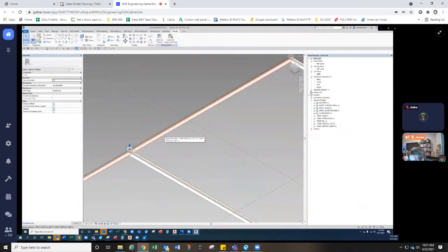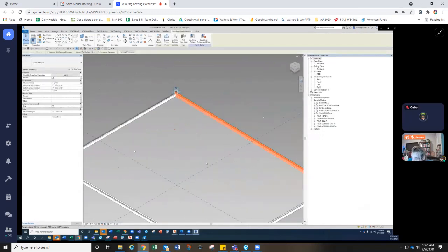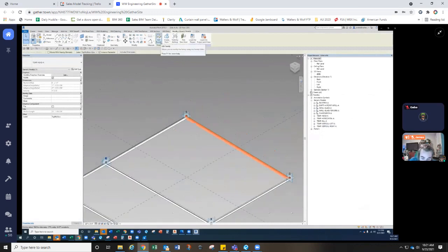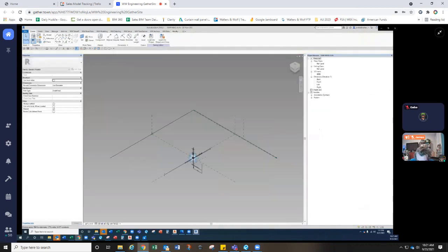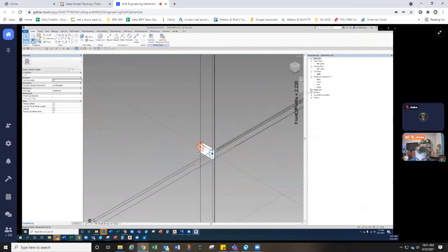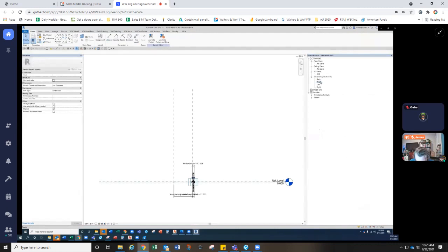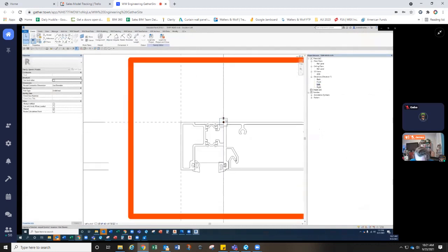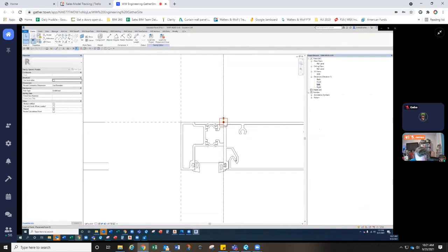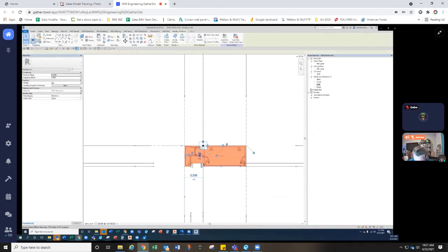I'd like to talk about maybe the mullions really quickly. We tried to set everything up in the same manner that the G units are, even though the templates look a lot different. The general theory behind everything is the same. So here we have one of our mullions. This is the head. We're calling it temp head for the sales team. When you zoom in here, you can see we have the image, we have the datum point at that location where those adaptive points are, and then we have a general shape that's been created.